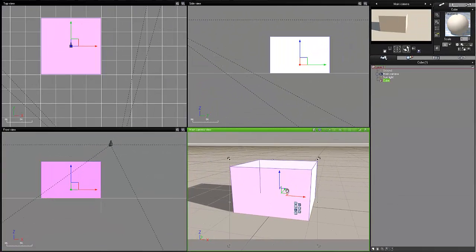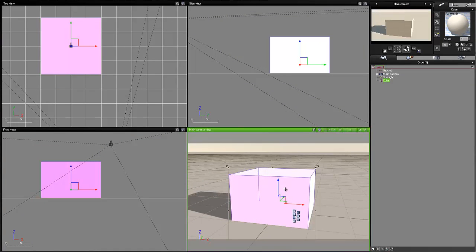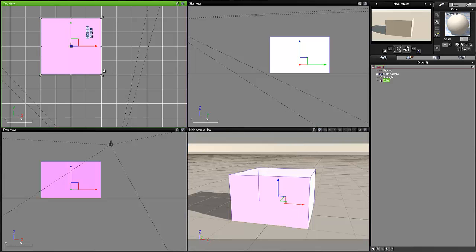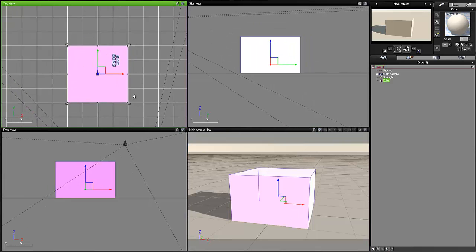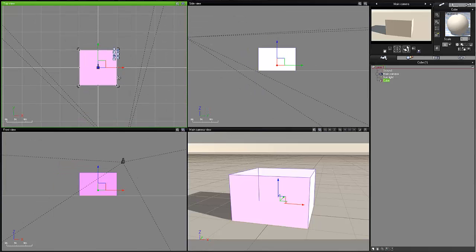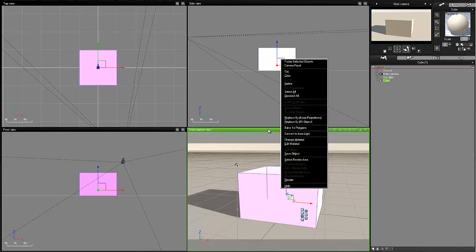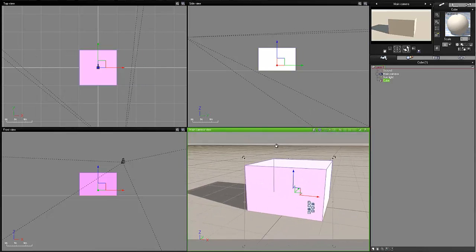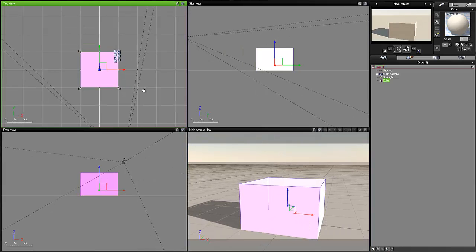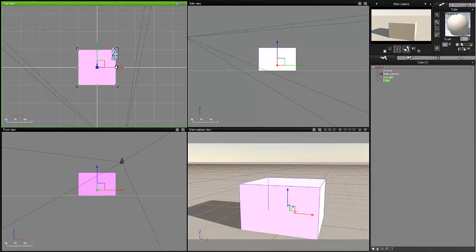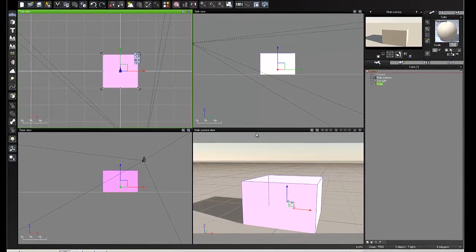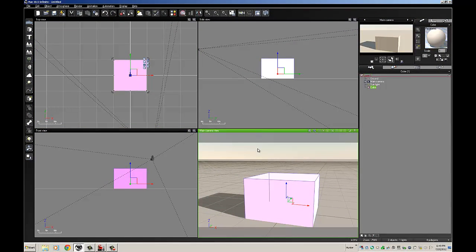And this is important to understand, because if you're placing objects only in the perspective view, you don't know how close to you or how far away or how far to the left or the right that object is. So you really need to understand that in order to place objects, you're really going to have to use these other three views to know where that object is in respect to existing objects in your scene. I've seen a lot of people try to just place objects only using this perspective view, and they're actually placing the object way out in space somewhere. They don't understand when they finally go to create an animation or they move the camera around why the object suddenly just disappears.